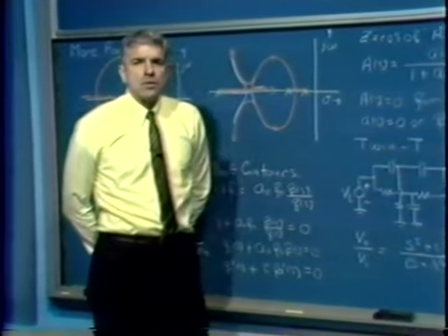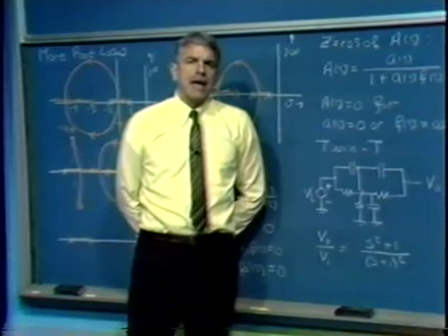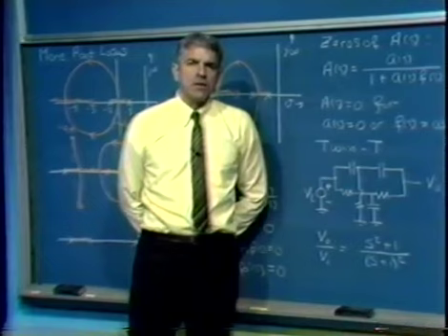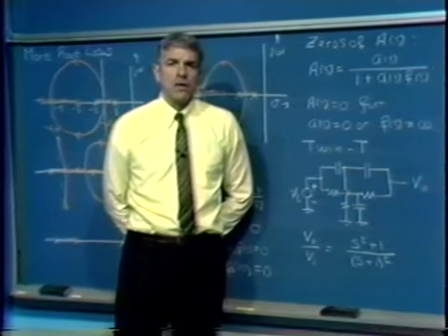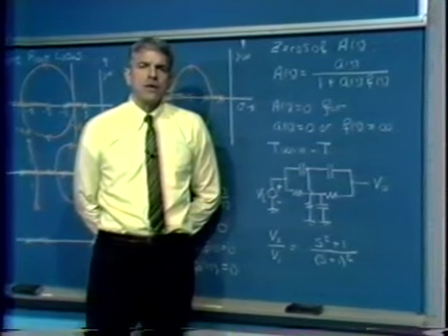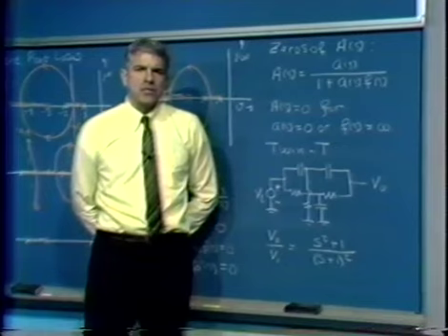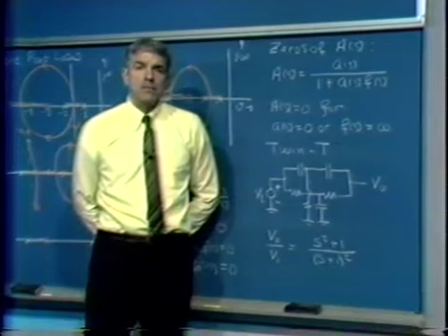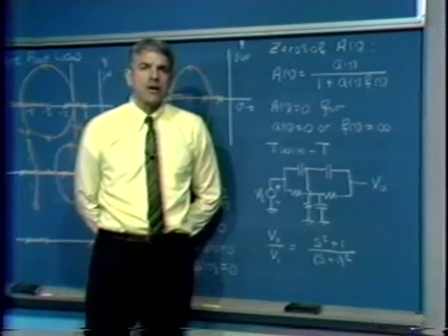Finally, I'd like to look in our continuing discussion of root locus diagrams at the zeros, the closed loop zeros of a feedback system. We started our discussion of root locus techniques by arguing that we were only going to look for the pole locations, at least initially, the closed loop pole locations. And as a consequence of that, we don't really have to worry about how the loop transmission is distributed between the forward path and the feedback path. However, when we're interested in system zeros, closed loop zeros, it becomes important how the loop transmission is distributed. So let's look at that problem for a moment.